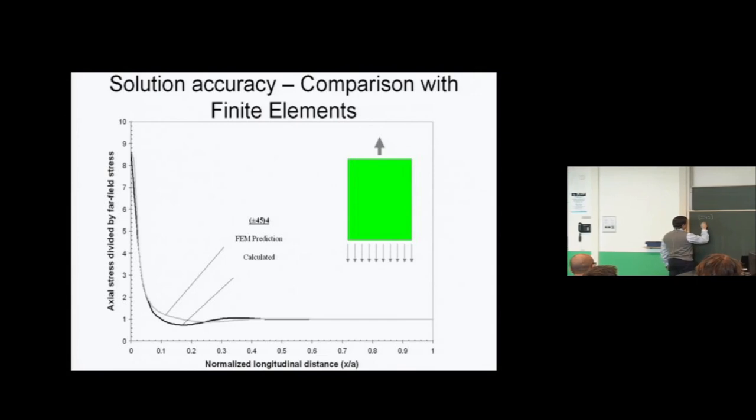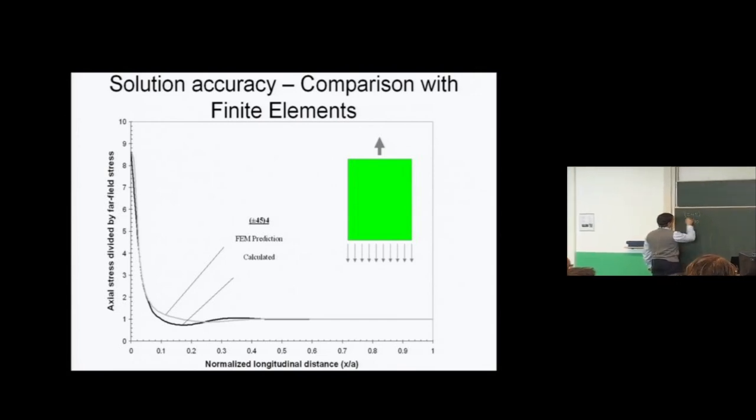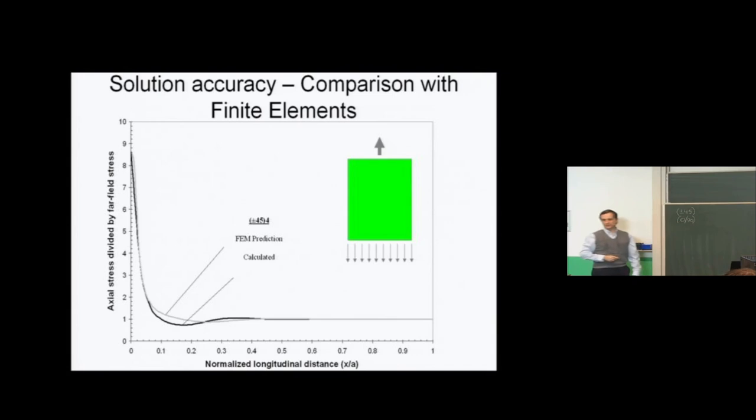And by the same token, if I ever write this in parentheses, that is a single ply in the 0/90 degrees. So basically, plus or minus 45 means that in a single ply, half of the fibers are going in the plus 45 and half of the fibers are going in the minus 45. That's this guy here. And this one is the same thing rotated by 90 degrees, obviously. So the example has only 45s, basically 4 layers of this thing on top of each other.